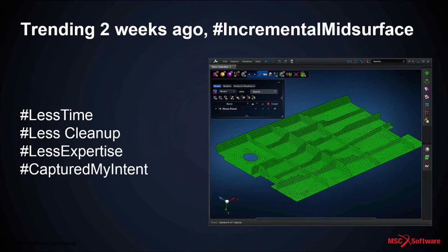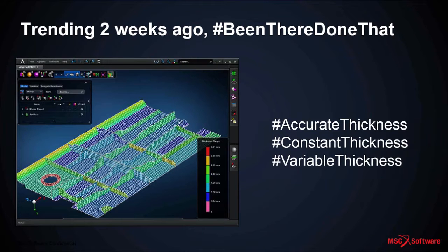If I'm going to defend my results, I want to have my intent represented in the model. So in addition to creating geometry, a mid-surface geometry and a mid-surface mesh, we also applied thicknesses. This is just one button click in MSC Apex. Actually, it's two. You pick the mesh, you pick the solid. So you map the thickness from the solid onto the shell elements. You get accurate thickness information for both constant thickness as well as variable thickness areas.